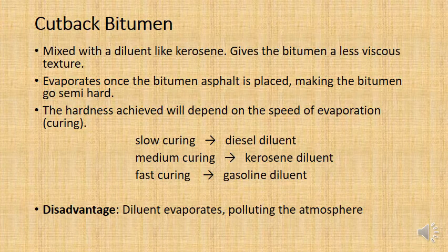It's going to be very hard to mix it. And then because of that, the asphalt is going to be clumpy. There's going to be big parts full of aggregate, parts full of bitumen. It's not going to be properly mixed. We need a way to make the bitumen less viscous, to make it more runny. How do we do that?